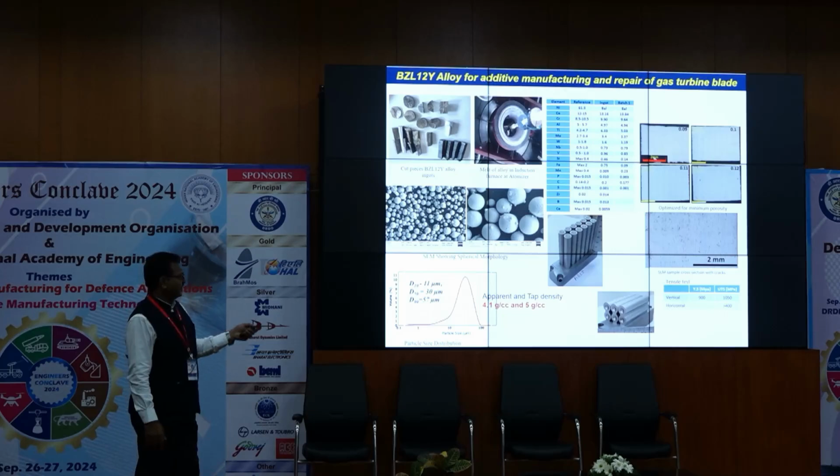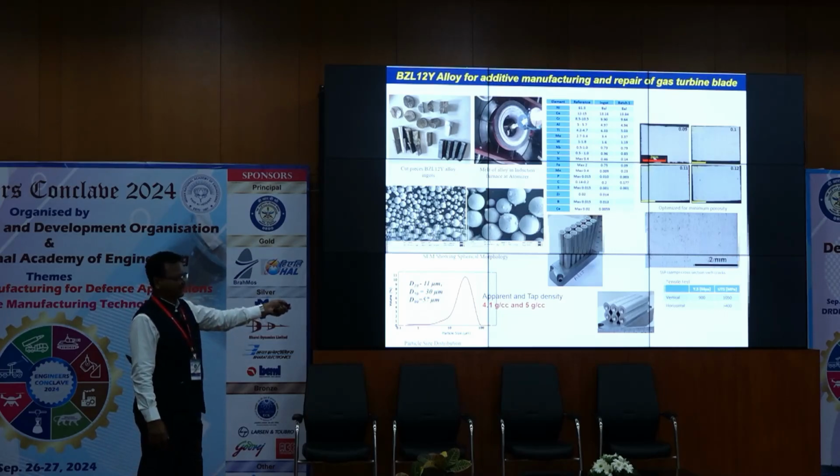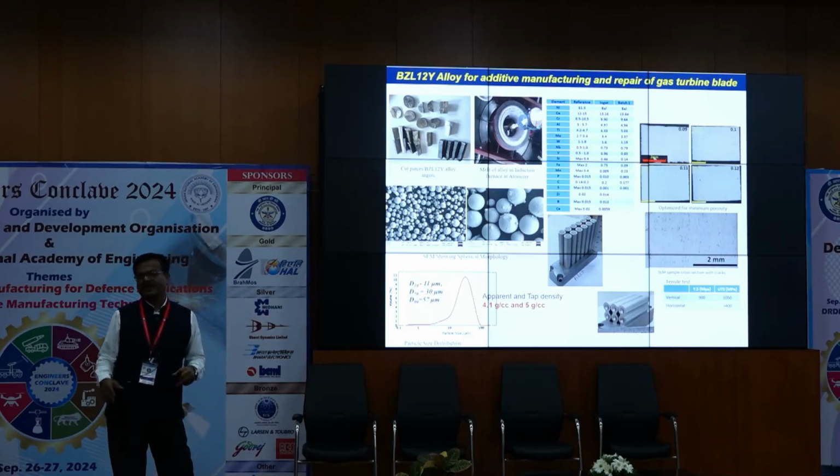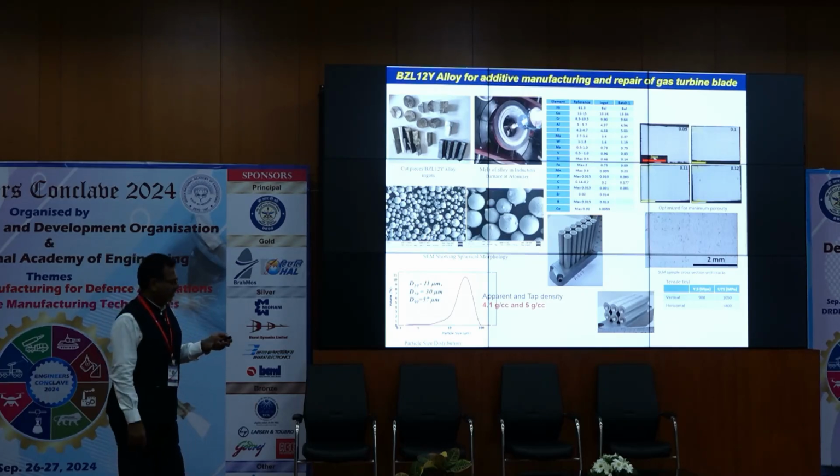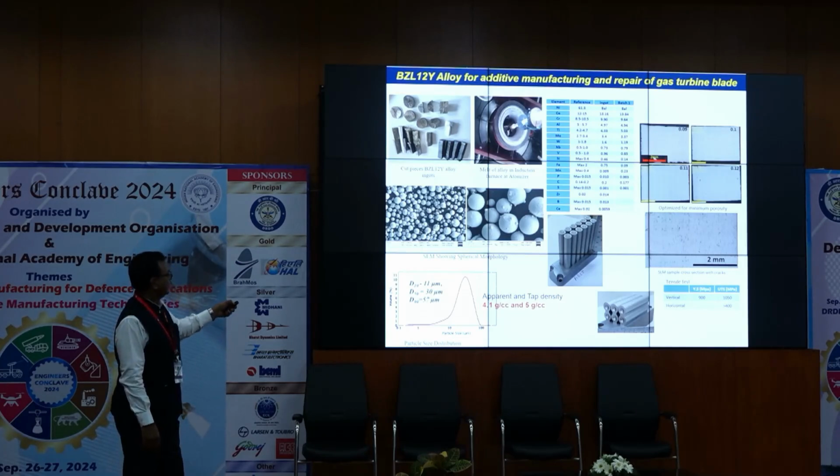But then we end up with solidification cracking. So this is a case where we now have to optimize the composition to remove the solidification cracking, or otherwise play with parameters like preheating or other things to avoid fast cooling rates, so that they don't crack. So still we are working on it.